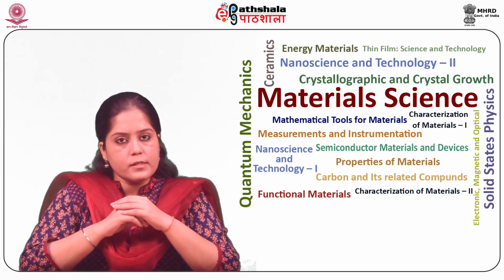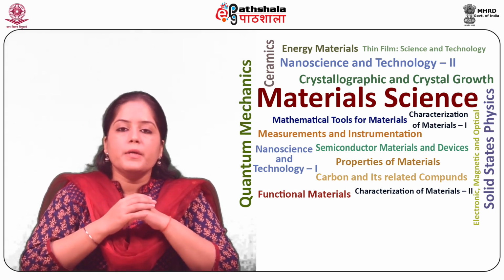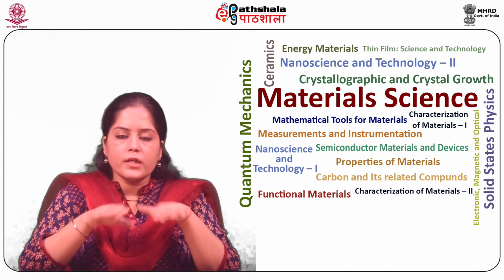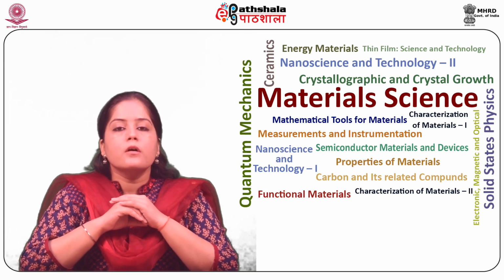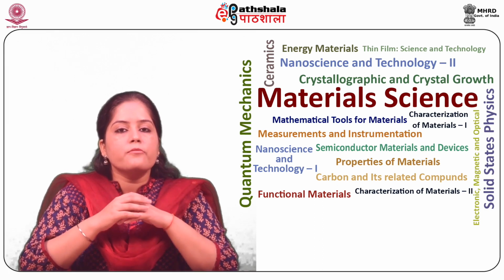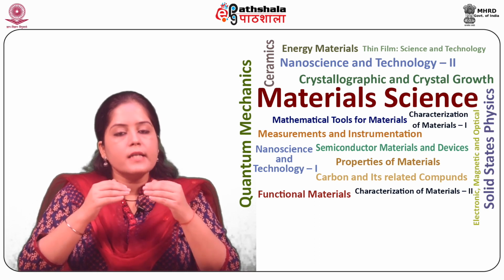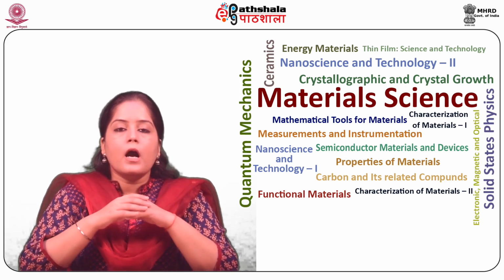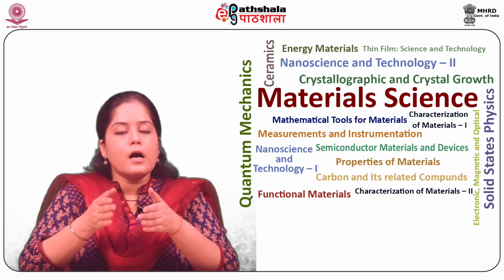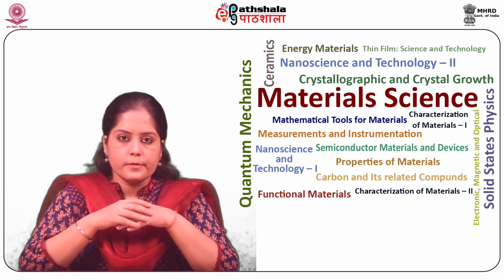Let us now discuss the programmable logic arrays, PLA. They exhibit a regular structure to implement combinational logic specified in sum-of-products canonical form. Some finite state machines are formed by PLAs only if the outputs are fed back to inputs through registers.